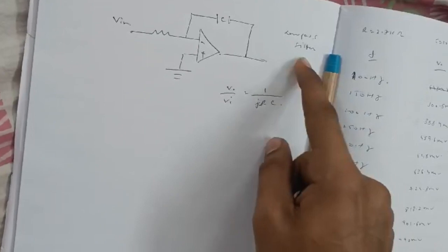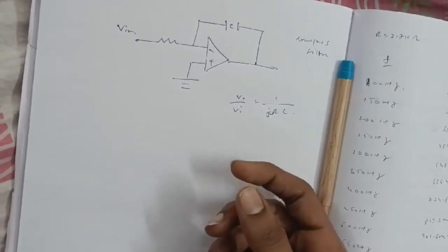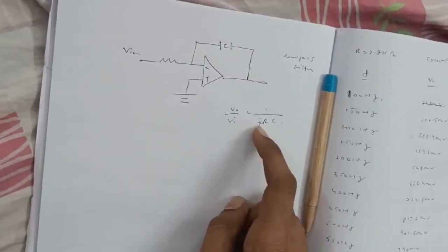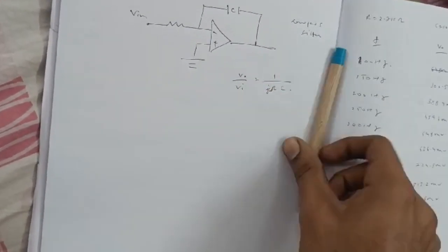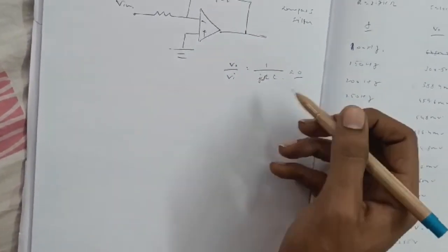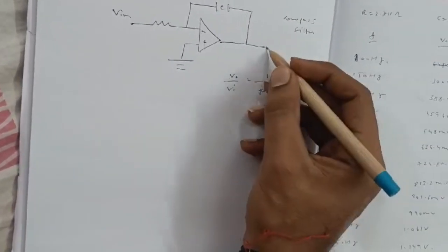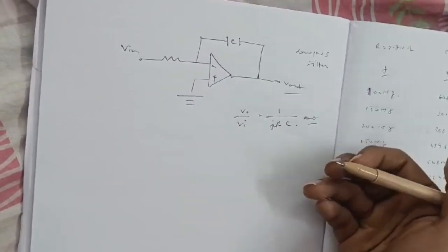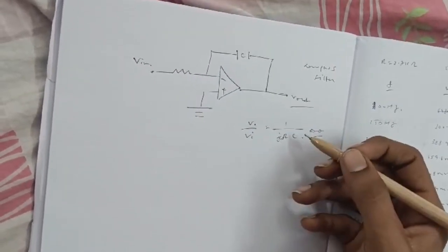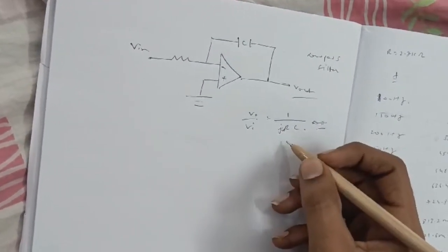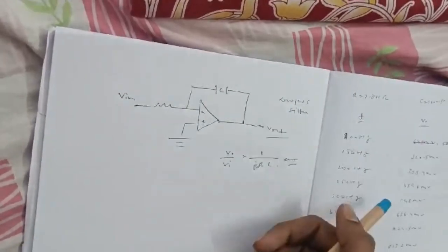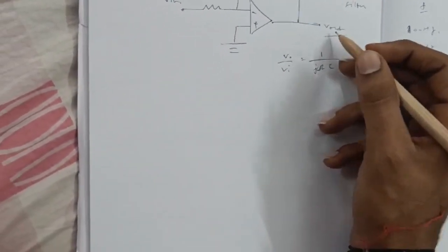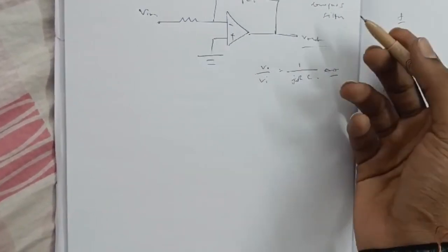Why? Because if we have very high frequency signals, that is, if omega is very high, then the gain function approximately becomes 0. So the transfer function is 0, and the output is approximately 0. It will become very small as the frequency increases. And if the signal is of low frequency, the transfer function will increase, which means the output of this circuit will be high.